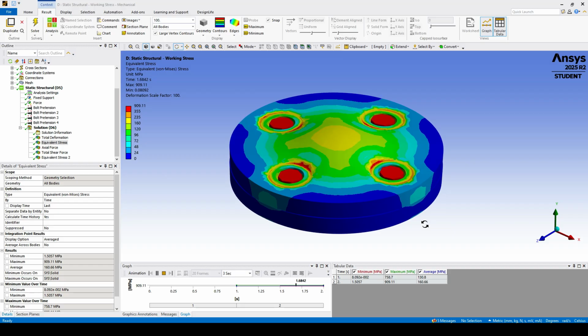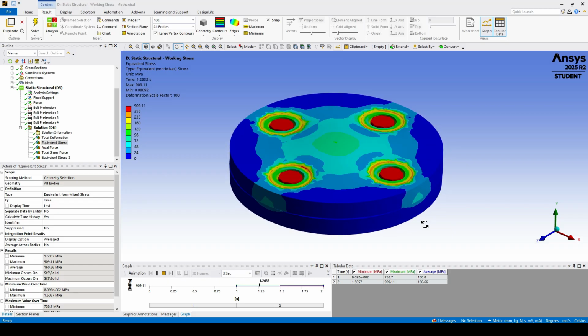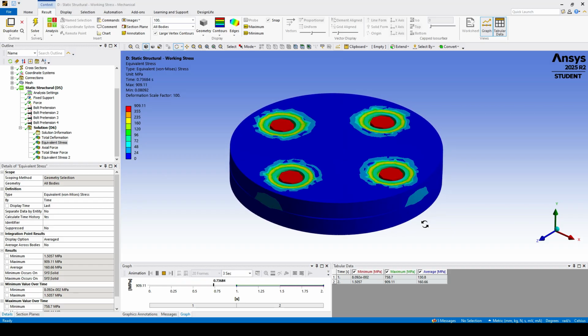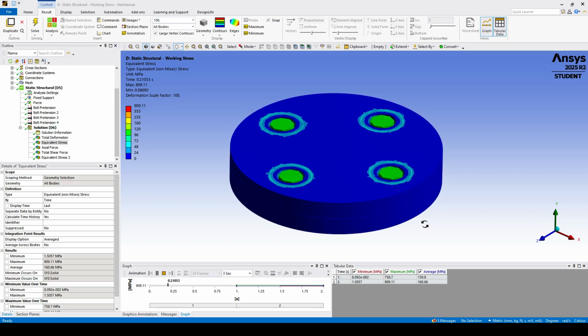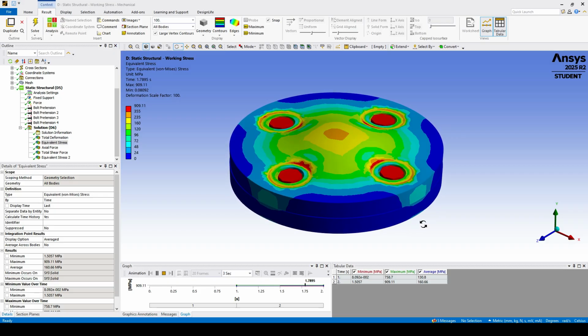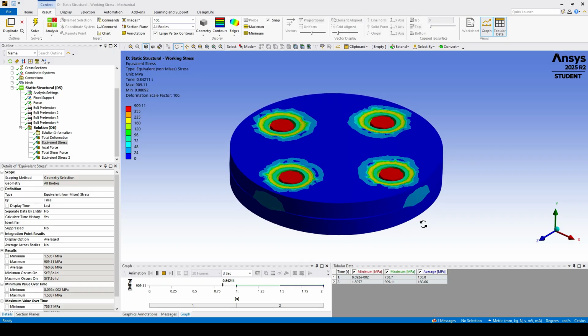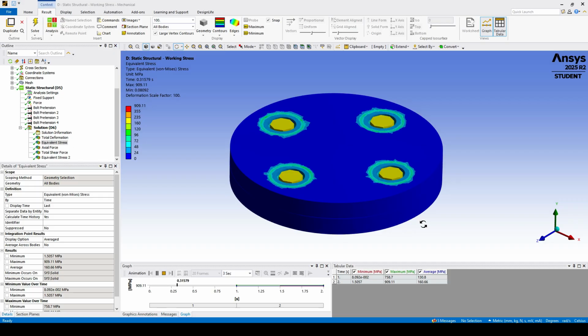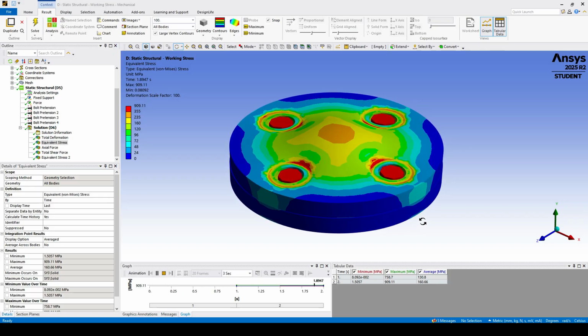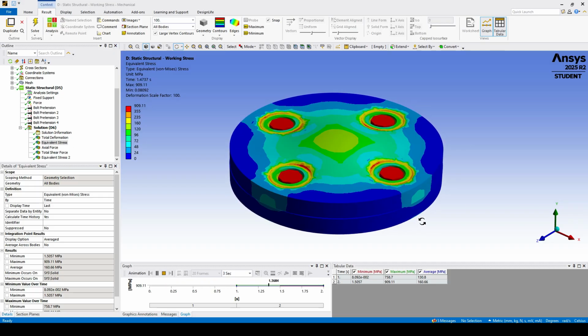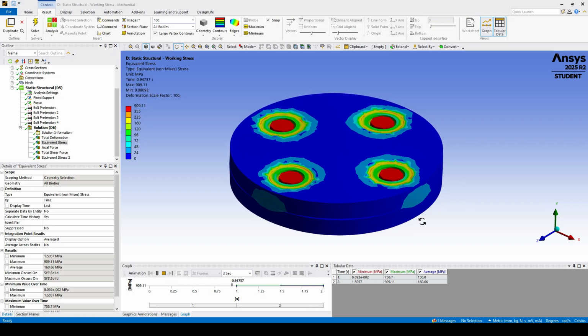Did you finish your finite element analysis and ANSYS tell you that the stress in your bolt is only 180 megapascal, for example? What if I told you that your bolts are already carrying several hundred megapascal of stress before you even apply the external load? So if you ignore that stress, your safety assessment could be completely wrong.